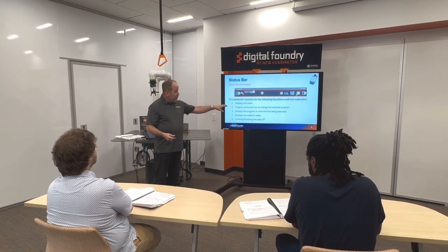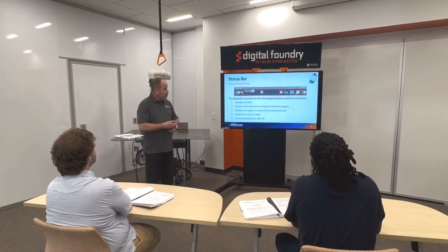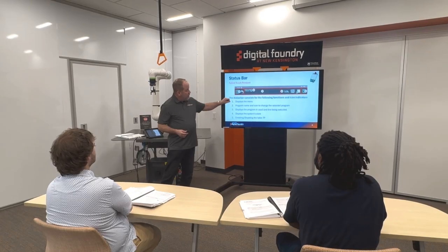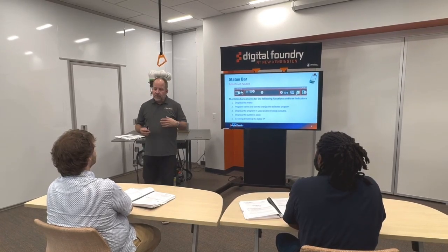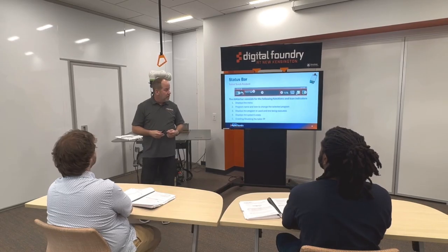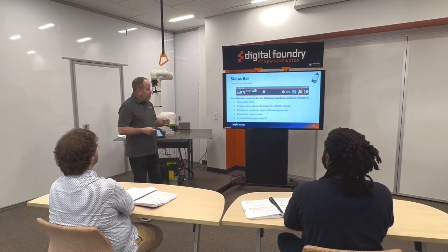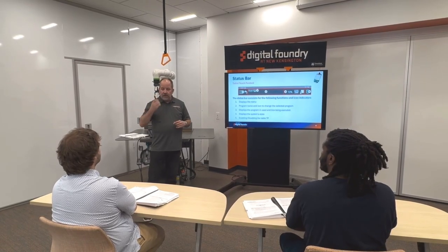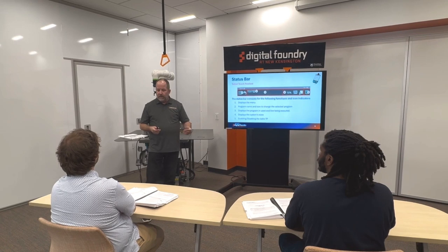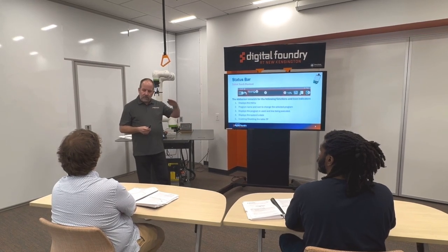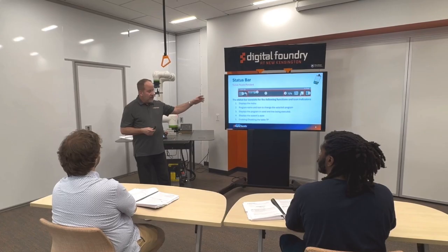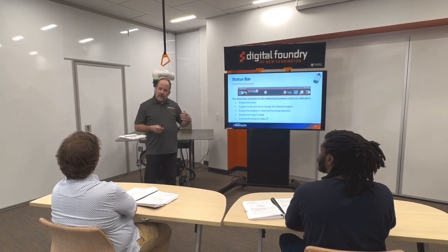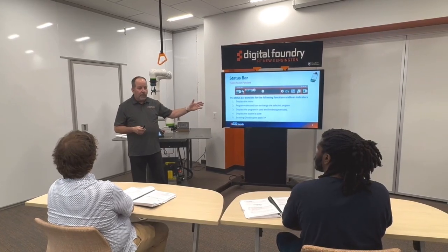2 is the program name and icon to change the selected program. So you could access different programs up here. You'll see the upside down arrow, and that can get you to maybe switching out different programs as you go. 3 displays the program in use and the line being executed. So like the handling tool, traditional robot from FANUC, you have lines of code. And here you have similar kinds of things, except you're looking at icons of code that allow you to see where you're at in your program.